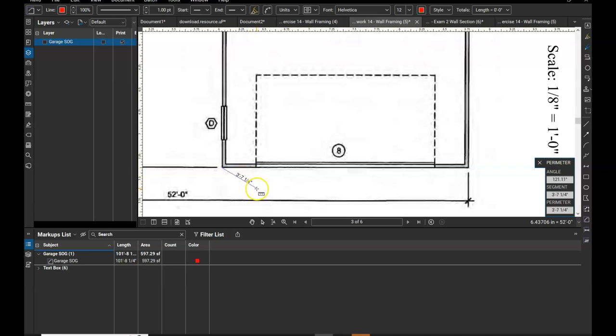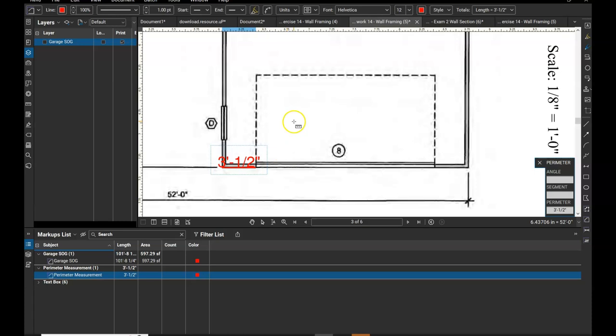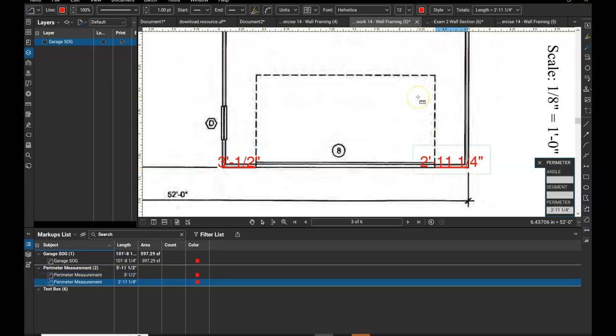So just when I'm drawing my line, I'm going to hold Shift to make sure it is a straight line. And so again, I just clicked once, hold Shift, click twice, and hit Enter. And we've got 2 dimensions right there. It should be pretty dang close. But again, here you can just see I'm like a ½ inch off, but it's totally fine for a linear foot. It should both be right at 3 feet. Here you can see it's starting to tally, but now we're just going to clean this up.